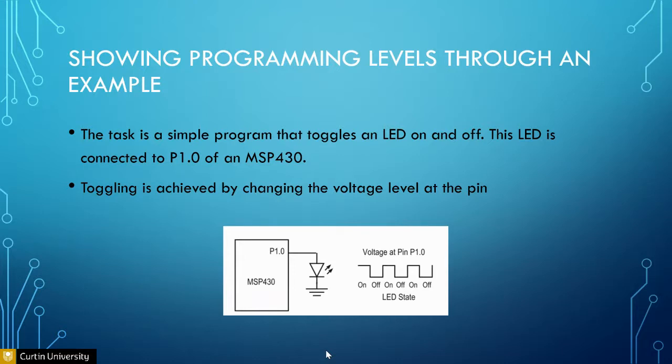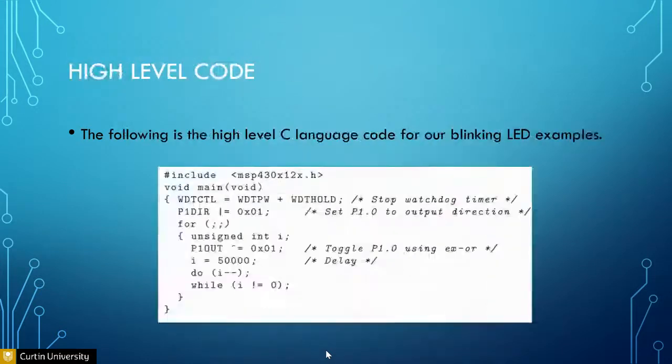P1DIR. How would you set P1DIR? You would set it manually. In C, you will set it as 0x01. Bear in mind that if you refer back to my tutorials, this is bit masking for set. Bit masking sets the last bit, bit 0, pin 0. So you set pin 0 as an output. The rest you don't care. If the existing pin number 7 is an output, you're not going to affect that. This is what we call bit masking.